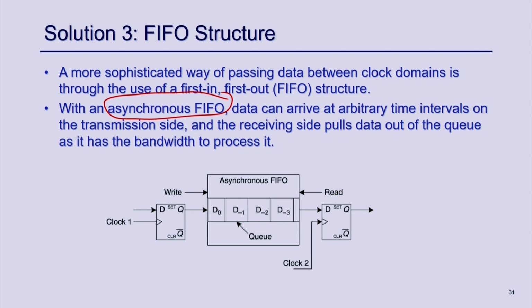It basically appears everywhere, right. Just think about a shopping mall where we have that billing point, that is, we have a queue, right. The speed of the person who does the billing may be different from the frequency in which the customers come. So, if the customer frequency is high, there will be a long queue. If the frequency of the biller is fast, there will be no queue. So, the frequency of the biller versus the coming customer are two different domains, and their frequency may be different, and we have a first in first out queue, and that is what this asynchronous queue is.